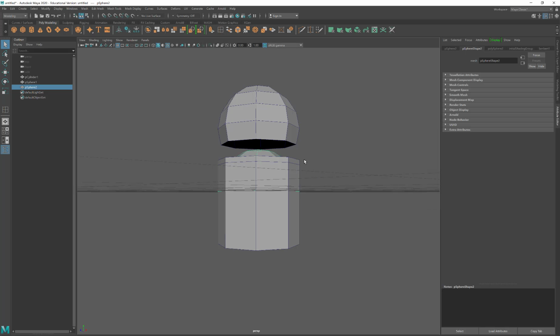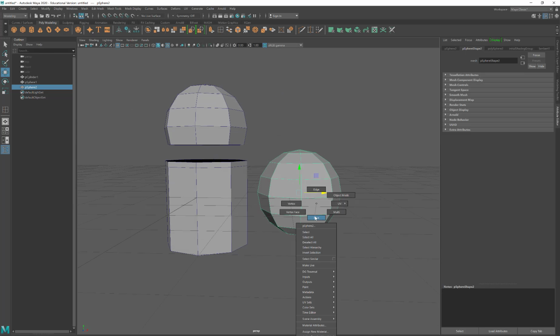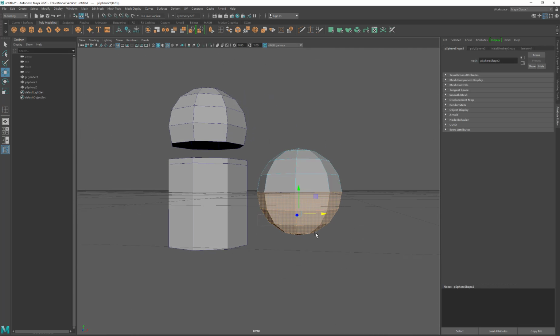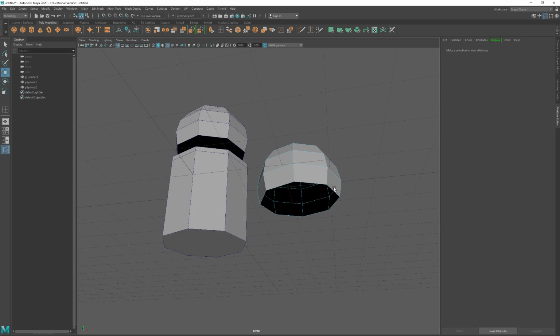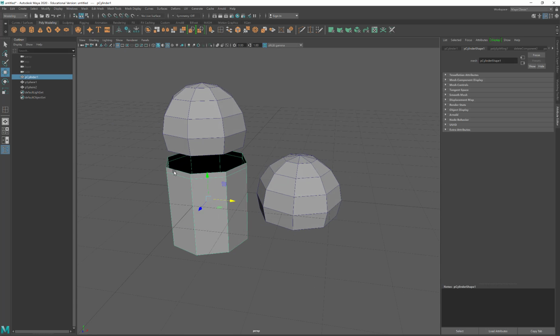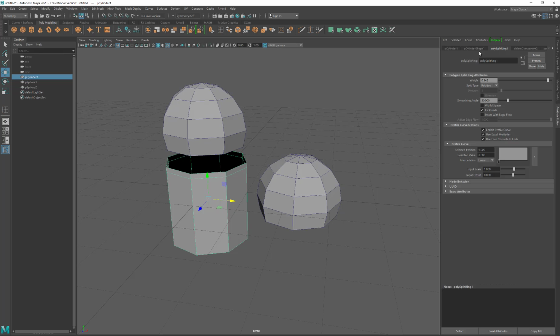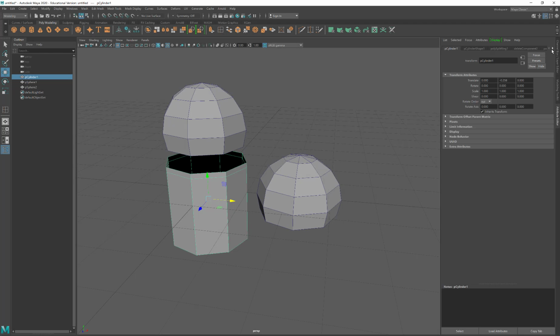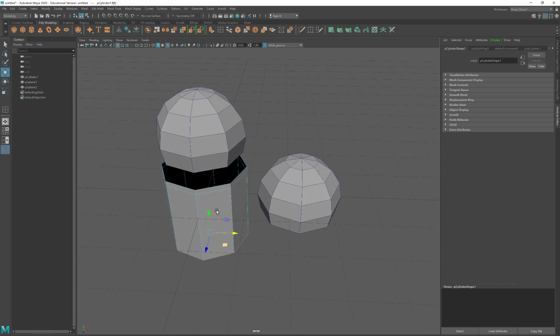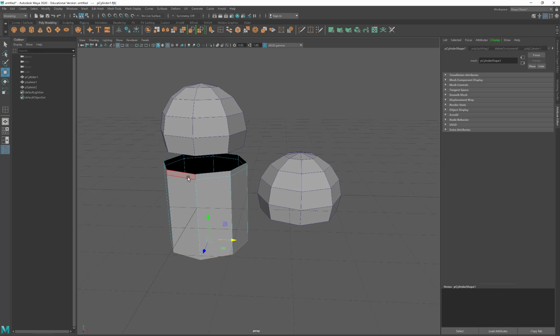And so I have an 8 by 8 sphere that I went into and right-clicked, and I selected all these faces just like this, and I deleted them, about this level. And I have no faces on the bottom, just edges right here. With the cylinder, I just have a cylinder with 8 sides. So it's very important that it's just 8 components, and no caps. I got rid of the caps, so where I had faces, I deleted them.